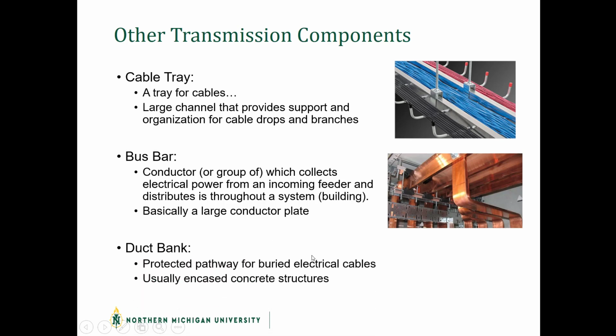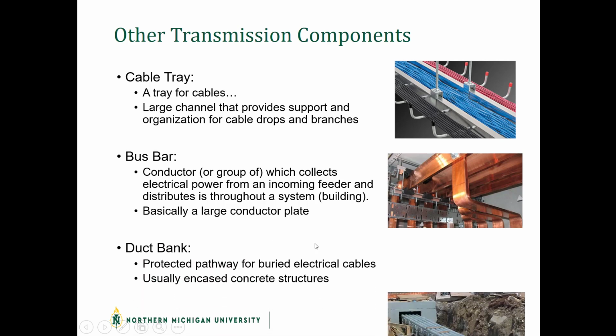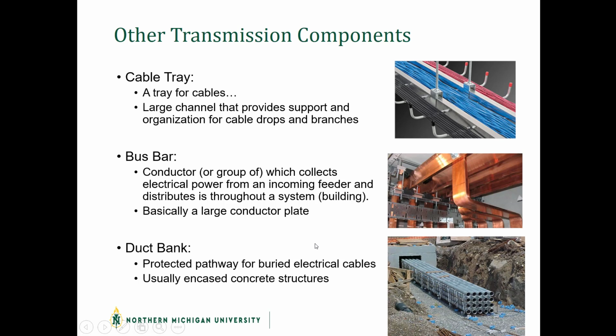Duct bank is a protected pathway for buried electrical cables. So generally we see these underground on the exterior of your building, running into the interior building, but a lot of times they're concrete encased, can be plastic encased, but normally we're talking big concrete encasements or steel encasements.